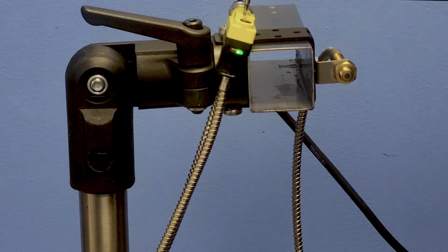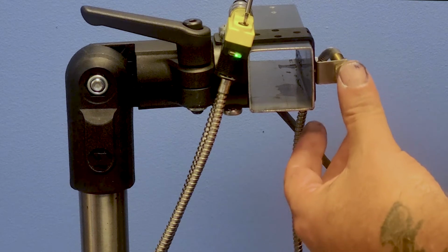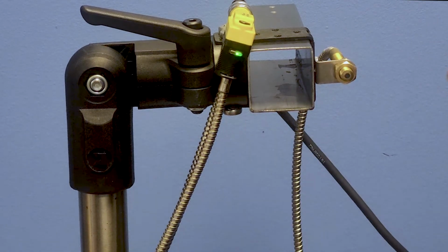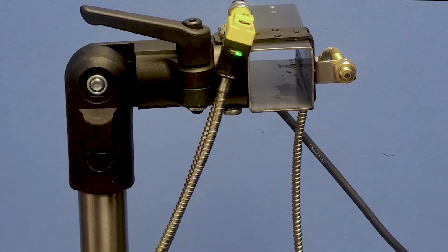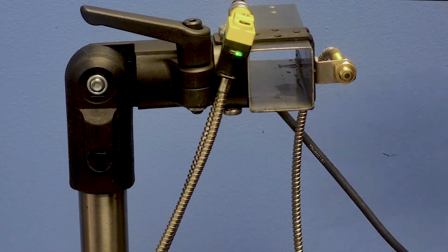So again, I can shut this off and you have nothing except for the solid green, and we're just going to turn it enough where we get solid yellow. So what happens here, guys, is every time our product crosses this photocell with a printer head in here, we will print.